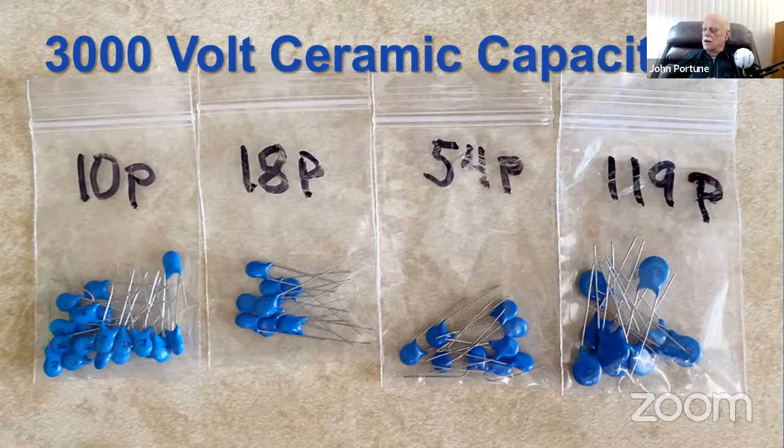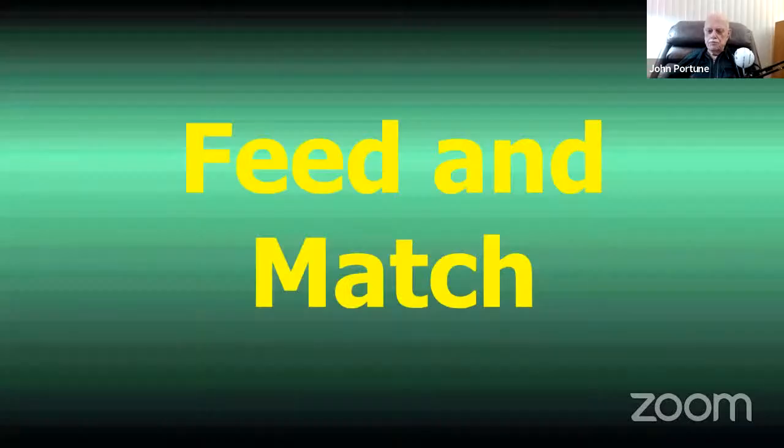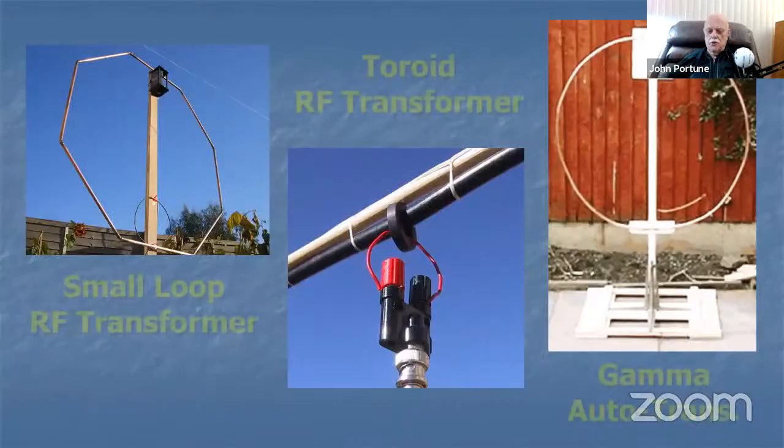You need about 100 pF of them shunted across the sliding pipe capacitor to make the thing get down to 40 meters. I'm doing a little addition. I haven't finished it yet, but I'm going to use this little knife switch to actually switch in those capacitors on the outside.